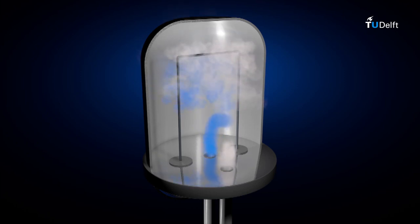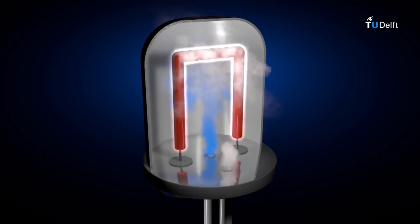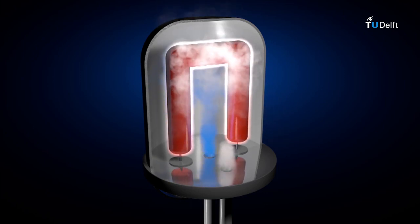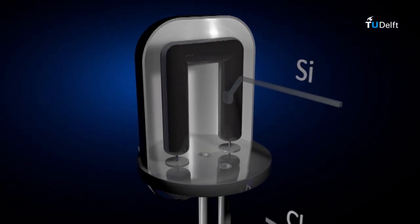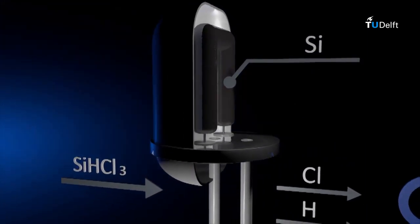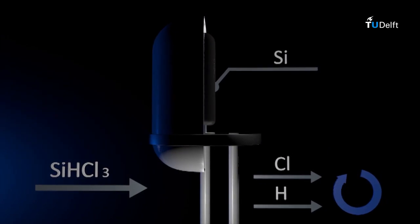The silicon atoms are deposited on the rod, whereas the chlorine and hydrogen atoms are desorbed from the surface of the rod back into the gas phase. As a result, a pure silicon material is grown, and this deposition method is called chemical vapor deposition. As the exhaust gas still contains chlorosilanes and hydrogen, these gases are recycled and used again. Chlorosilane is liquefied and distilled and reused. The hydrogen goes through a cleanup process and is recycled back into the reactor.